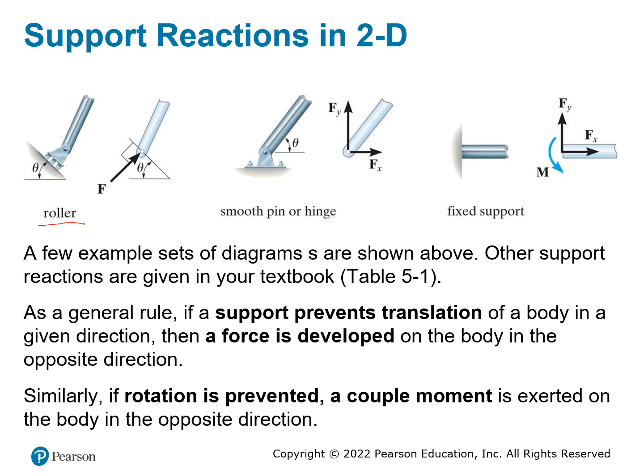If you have a roller, we're going to assume the roller only has the supporting force, just like you put a ball on top of a ramp. It only gives you one single point of reaction force. So the force is always going to be perpendicular to the contact surface between the roller and the surface. So that's the roller case.